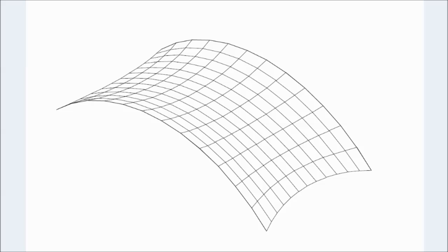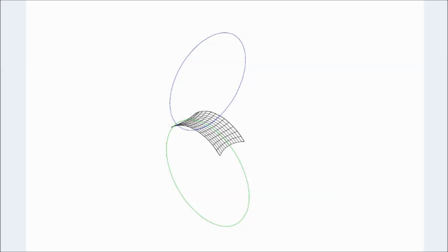A tensile structure's shape is maintained by the balance of two hoop stresses along the principal directions of curvature. These are shown in blue and green in the drawing. The hoop stresses are the result of pre-stressing the structure by means of compensation and also of the structure's specific shape, which determines the size of the two hoop radii. When loads are applied, this could be wind suction, snow load, or any other natural stress applied to the structure, the load causes one of the hoop stresses to increase and the other to decrease. This change in stress will stretch or shrink the material, giving it a different structural shape. That, however, is a further complication which we'll ignore for now.